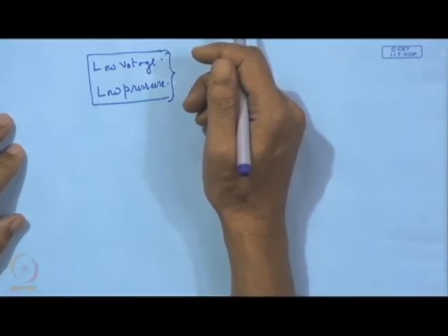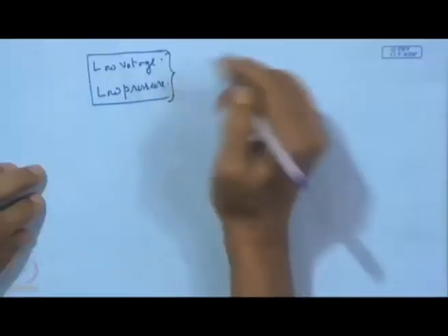However, for conducting material also it is possible, but in that case we need a blocking capacitor as a peripheral support and also a matching network. These are two important things with the sputtering device. Now, low voltage and low pressure are the two important things one can identify, extremely advantageous to carry out or to conduct this sputtering process.